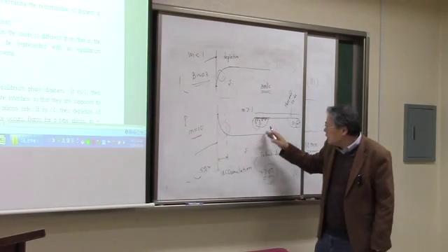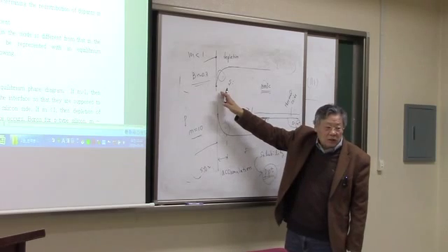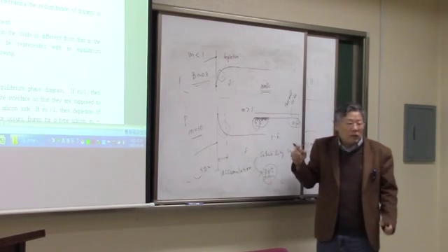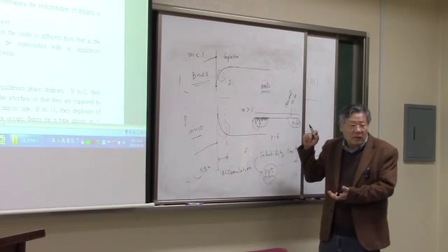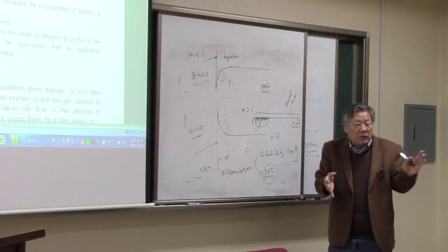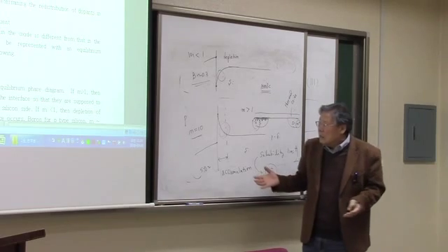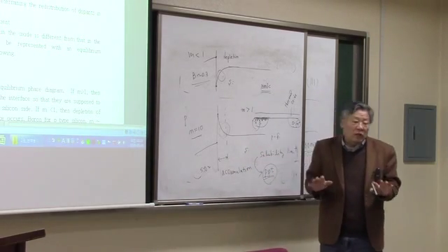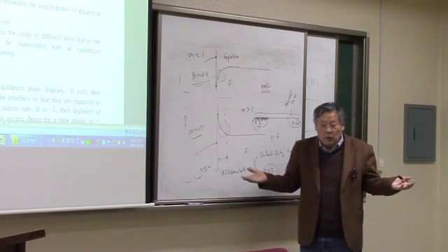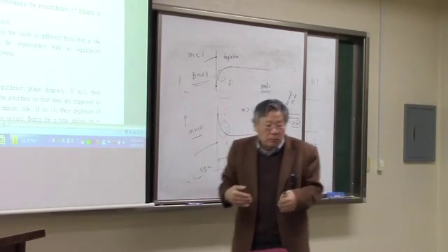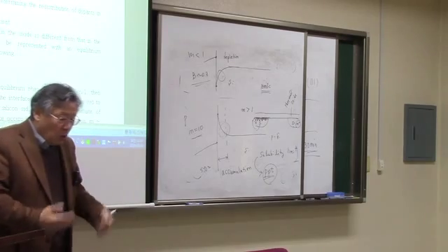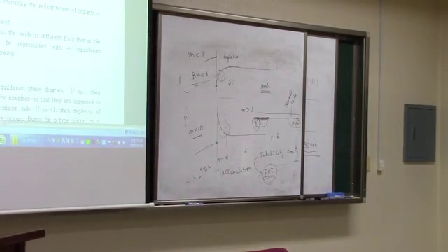Now what happens if you dope this source and drain with boron? You are going to have a depletion because the M value is 0.3, less than 1, right? Then if you have a depletion like that, of course we are going to increase the surface resistance of the source and drains because you have a smaller amount of boron than what you put during the pre-deposition and drive-in. So in modern transistor fabrication, we do not want to grow oxide, especially thermal oxide, after the doping. We want to make a thermal oxide before, and it is very much preferred, and there is a theory behind it. We want to grow the oxide before any doping process. So dopant distribution is very important.